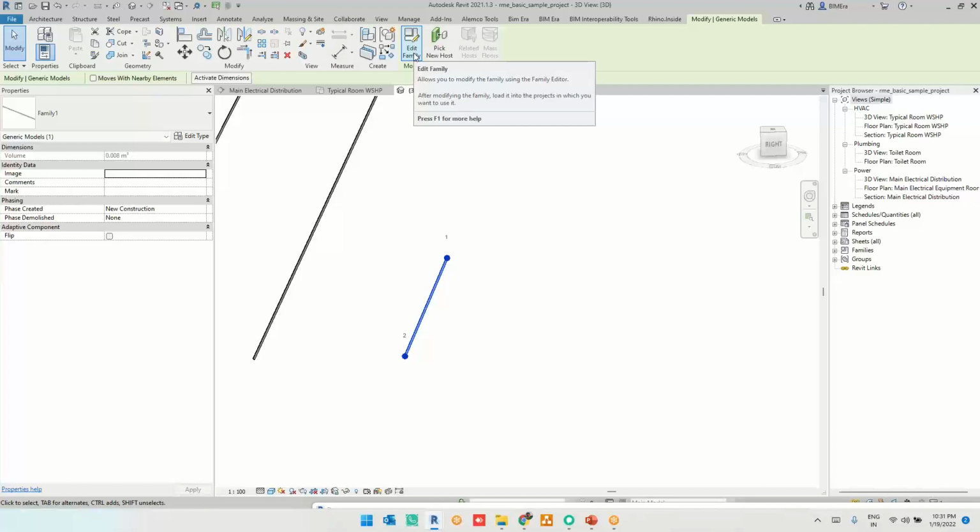This is a Dynamo Revit geometry object, a component, because it's a Revit family. So because it's a Revit family, you can edit this. But if it is a geometry object generated by Dynamo, there is no edit option. There is no such point over there.